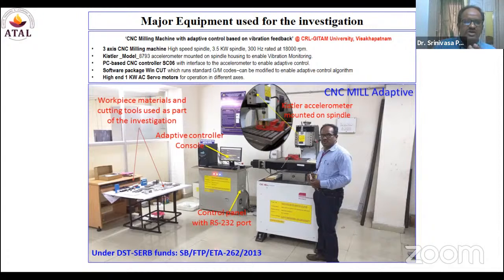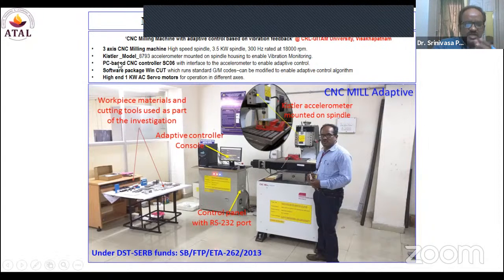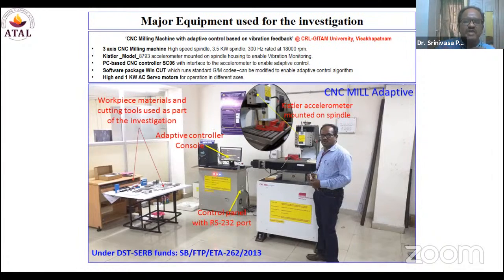Due to the presence of this Kistler accelerometer, its objective is to detect whether the machine is in running condition or not. Whenever you activate the particular icon, it will start collecting the data. Then, as an operator, you need to transform this information into a quantified vibration parameter, and that must be done in the quickest possible time.